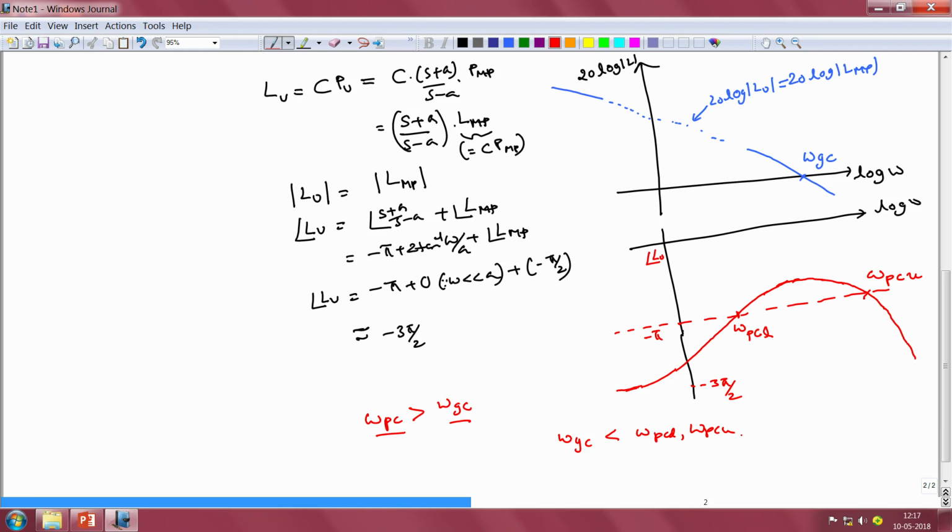That may be our naive conclusion, first guess about what is necessary in order for our closed loop system to be stable. But we have no logical arguments to back such a claim, and that is because, as I have repeated in the past, the Bode plot is by no means the right tool for us to determine the stability of a closed loop system.